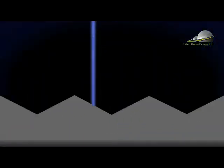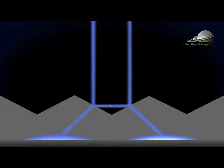To prevent this reflection, the surface is etched and roughened in a chemical bath. If the cells are put under a microscope, one can see the resulting pyramid structure. With this fine pyramid structure, light is refracted multiple times, allowing incoming light to be used far more effectively.